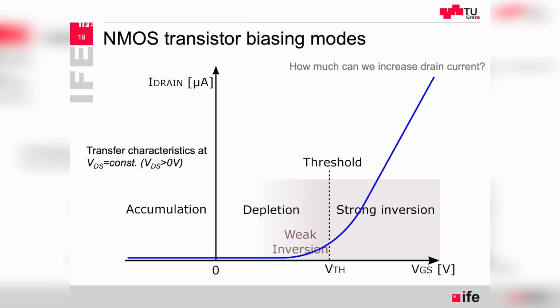Eventually, yes. It's possible that we apply too high voltage that the gate oxide breaks down. Anything else can happen? Even if it doesn't break, something else might happen before the gate oxide voltage is too high and it breaks. What else could happen?